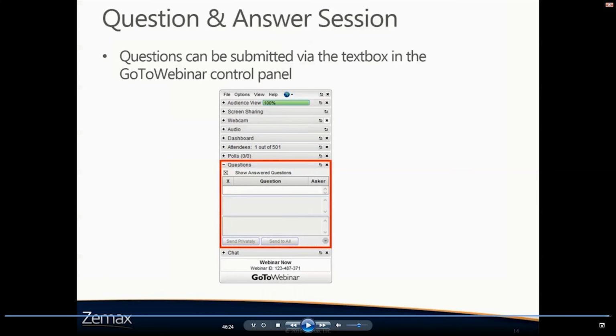And when you apply the Lambertian scatter profile, in order to make sure that rays will scatter both in reflection and transmission at a volume interface, if you have ray splitting enabled and some portion of the energy would be reflected and some portion would be transmitted, then essentially what OpticStudio does is it first calculates the specular ray paths. So if 20% of your energy was going to be reflected and 80% would be transmitted, it calculates the energy and orientation of those ray vectors, and then we apply the Lambertian scatter model to scatter about that specular ray path in each case. So we do actually apply the scattering both in reflection and transmission at interfaces that have both of those. With certain scatter models, you do need to apply those settings separately.